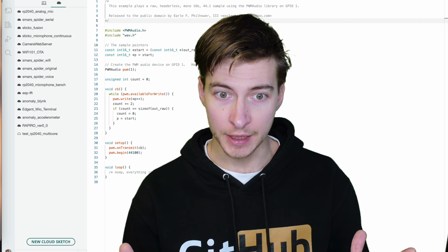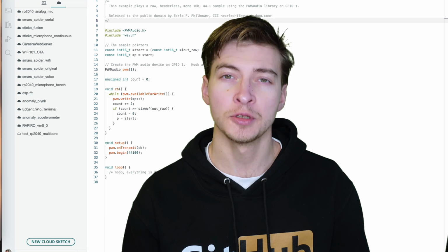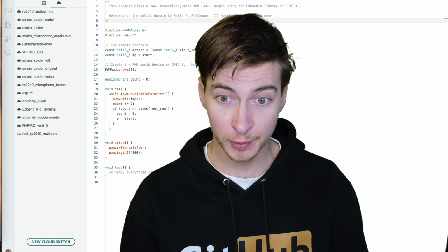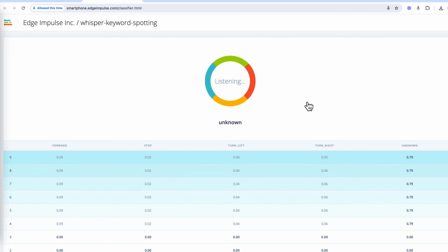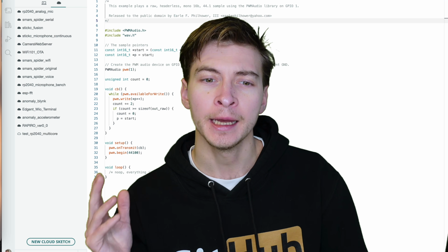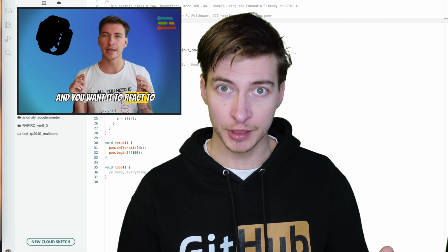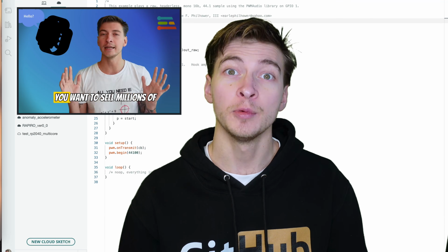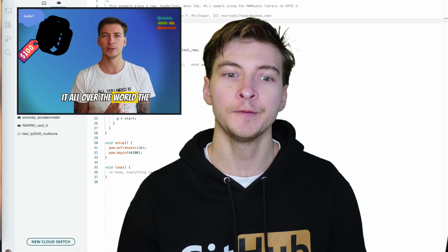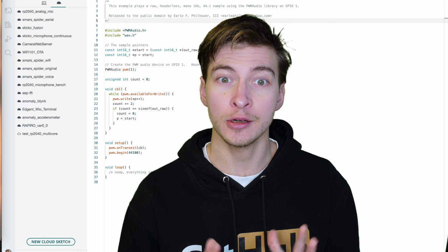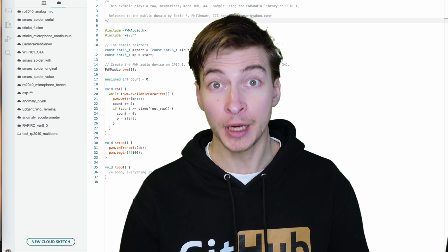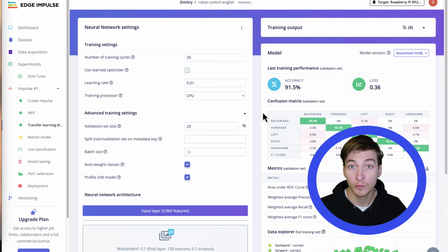And for the last piece, let's use the audio input to do something actually useful with it and recognize keywords with a machine learning model running on RP2350. I made a video about using synthetic data to easily train a keyword spotting model in under 10 minutes with Edge Impulse. You can follow the guide to train your own model or simply take the public project that I shared, which I used for robot spider control.